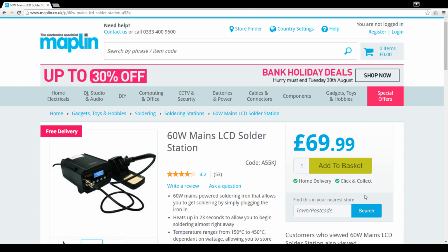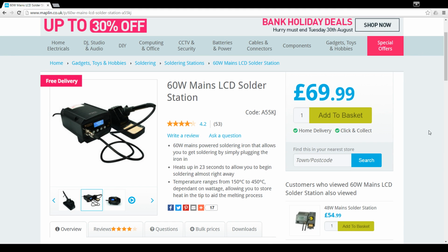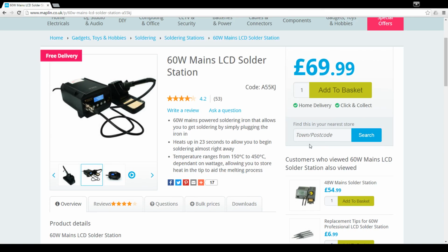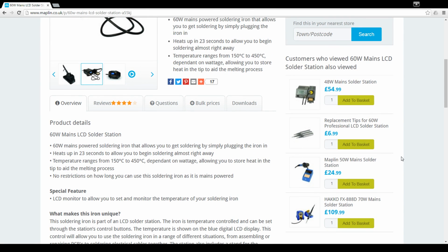So John, back to your question about what equipment you should get for electrical engineering. I would recommend a soldering iron. Let me just quickly go to the Maplins page, because while I'll show you on Maplins, you don't have to go via Maplins. You can go via whatever distributors in your area. Most of the equipment I've got is incredibly cheap, but essentially a soldering iron, any will do. Obviously not something that's ridiculously low wattage. Around about 50 watts here will do.